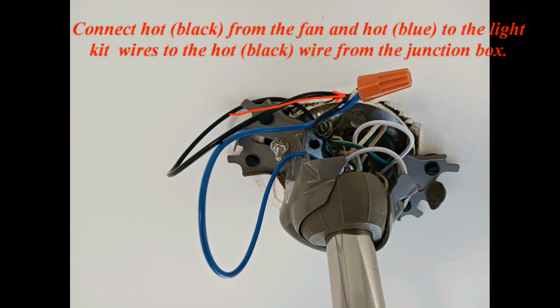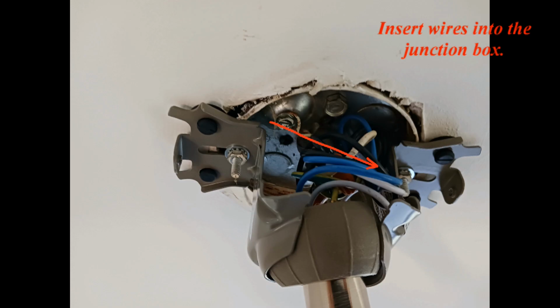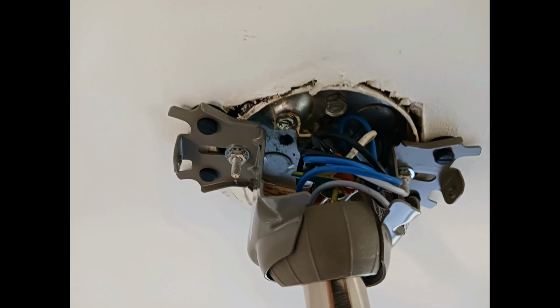Connect hot, black, from the fan and hot, blue, to the light kit wires to the hot, black, wire from the junction box. Insert wires into the junction box. If the existing fan had 2 switches controlling it, the junction box shall also have another wire, usually red. In this situation, connect fan hot, black, wire to the hot, black wire from the junction box, and also connect the hot fan light kit, blue, wire to the other hot wire, usually red, from the junction box.